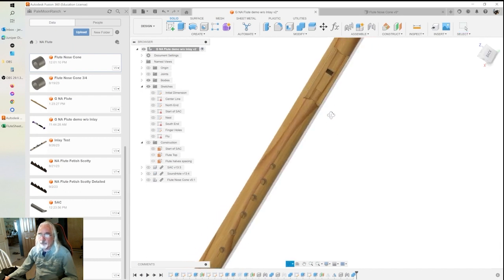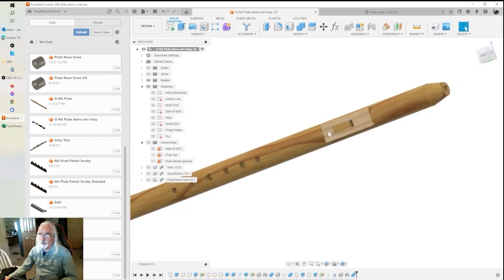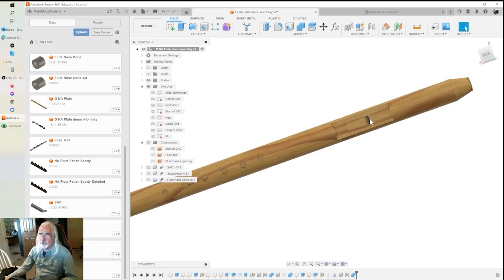Then I also don't want it diving into these holes. And you'll notice that the sound hole went away. That's because that extrude is now all the way through there. But this one's still open, and I don't want it diving in here. I've already carved this hole, so I don't want it messing with it. I don't want it to touch it. So I'm also going to turn off that cutting tool that I had there. I'm going to suppress this component that I pulled in, and that'll automatically suppress the join and the cut. Okay, so I'm going to suppress that, so that hole goes away.